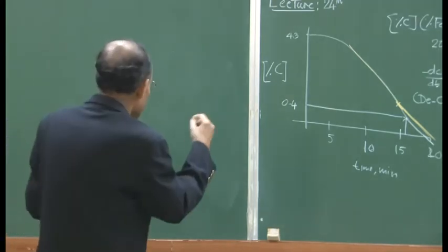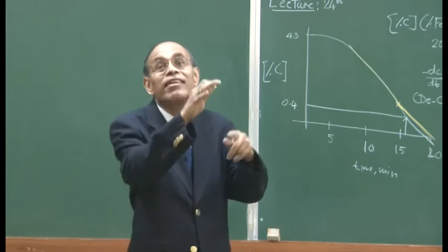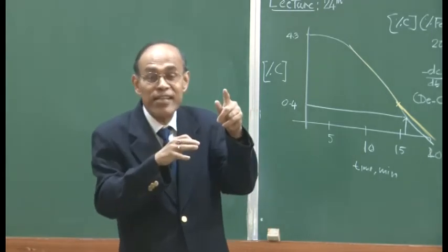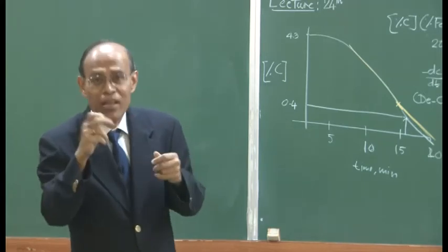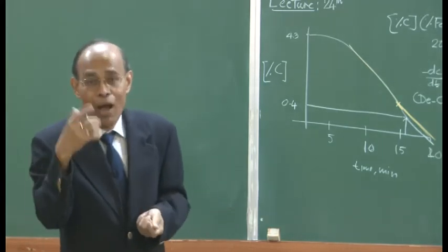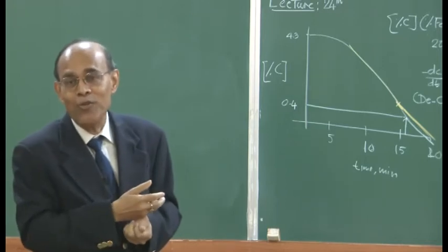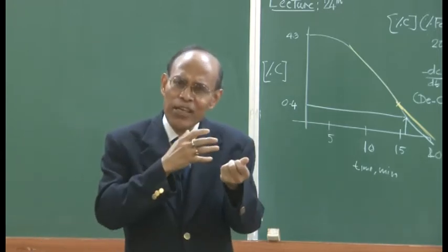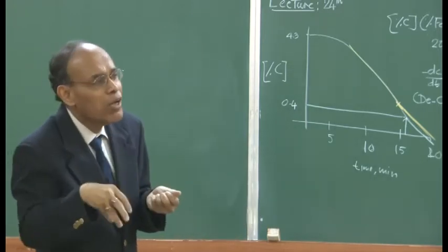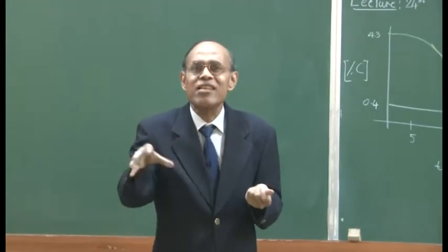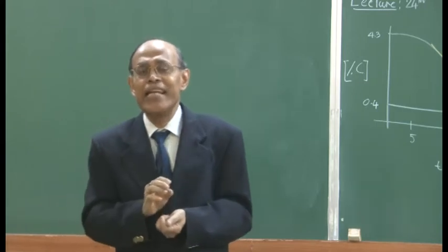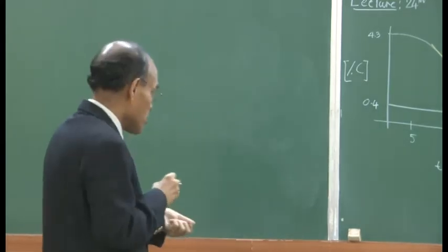Okay? So, the iron oxide content of the slag can reduce or increase because one system has started to operate much closer to the equilibrium. If a system is more intensely stirred, I will expect that it will operate very close to the equilibrium. If a system is incompletely or not coherently stirred, or not well stirred, I can expect that there are going to be inhomogeneities in the system, and therefore the chances of hitting equilibrium are not going to be that much.